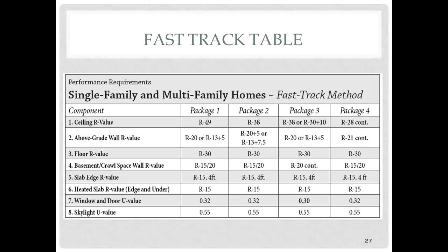Package 3 allows you more flexibility on attic insulation than package 1 does, and it basically makes up for that difference with basement insulation. The requirement there is R20 continuous, and also you'll notice that that package requires slightly more efficient windows. So if that system works better for you, you might prefer that package.